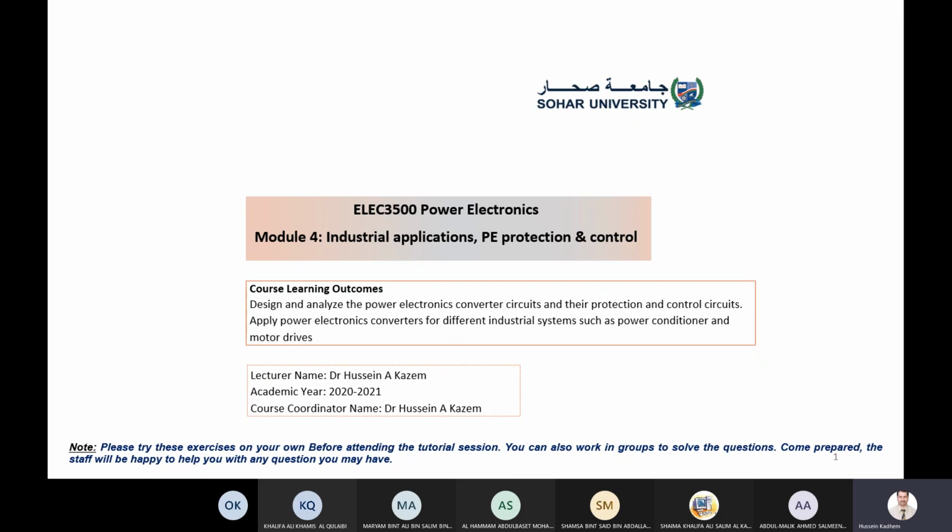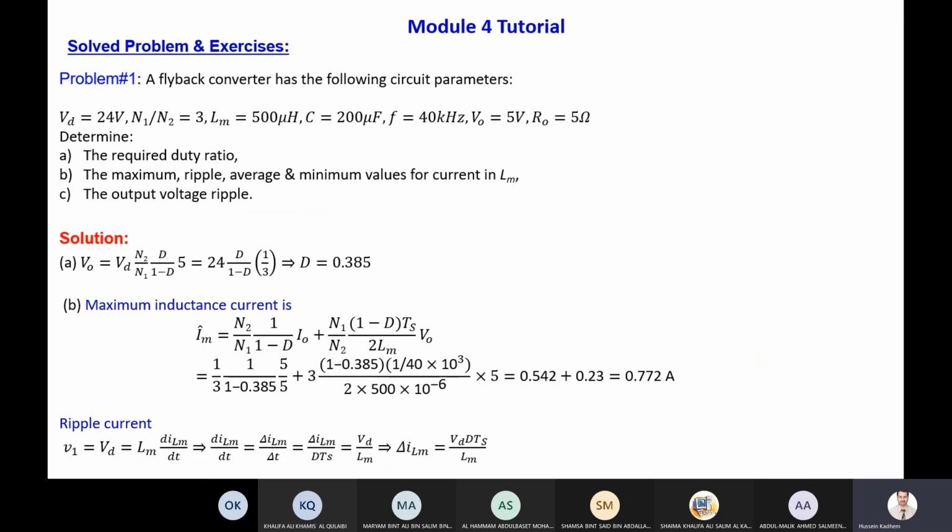I share it. Okay. Now you remember last time we talked about DC switch mode DC power supply, and we started with the first type, which is the flyback. Flyback is just an improvement made to the buck-boost converter. So it's a buck-boost converter, just we improve it by using an oscillating, high frequency transformer. Now I have here a few problems on flyback today, and we continue tomorrow.